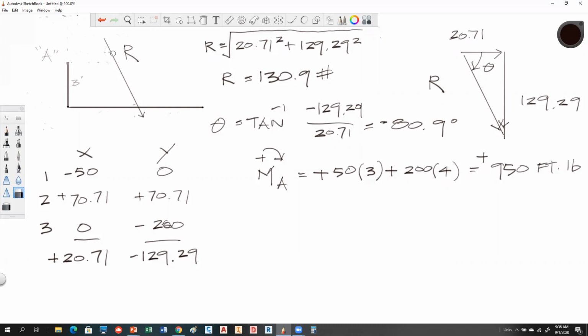So we're back into that same problem. We have to solve this perpendicular distance here, okay? And that's almost impossible. We don't know that. But this is where you can use transmissibility, and this is a little tricky. Let me draw something here. All right. This vector is composed of two vectors. A vector going down